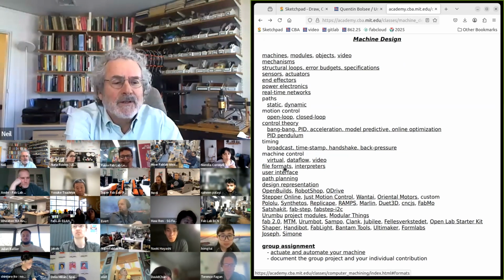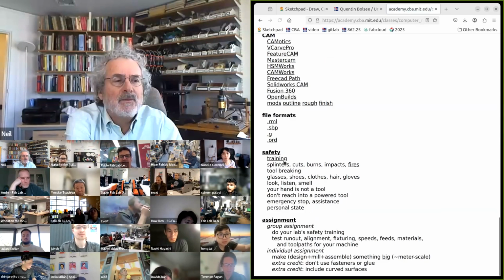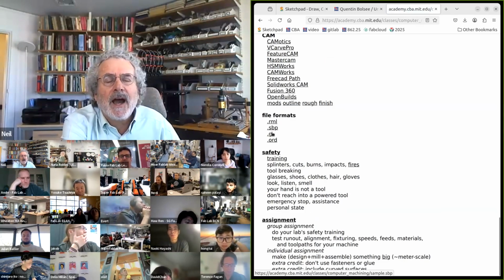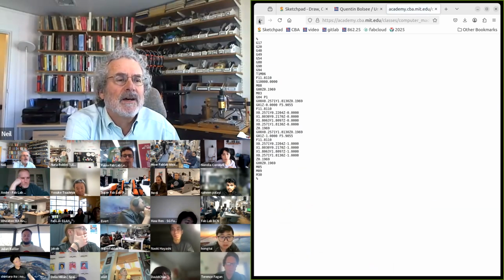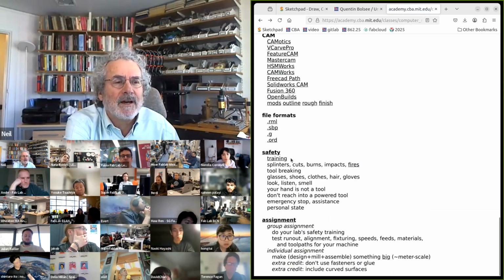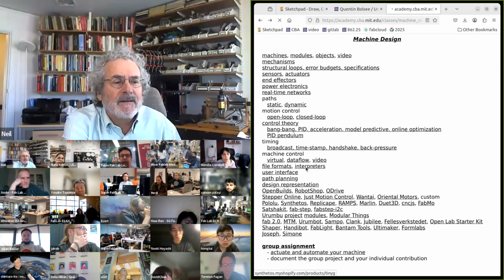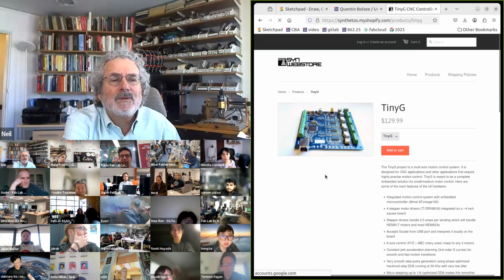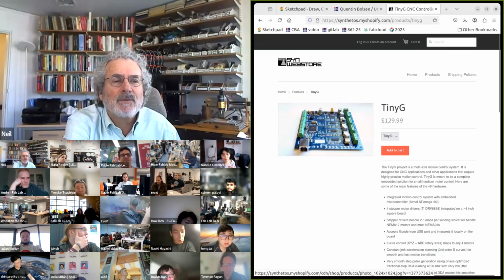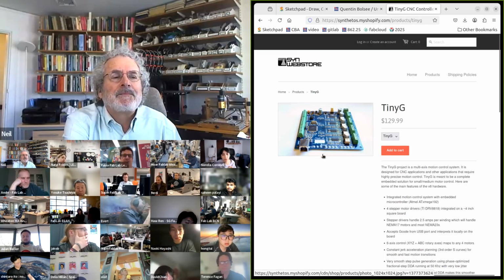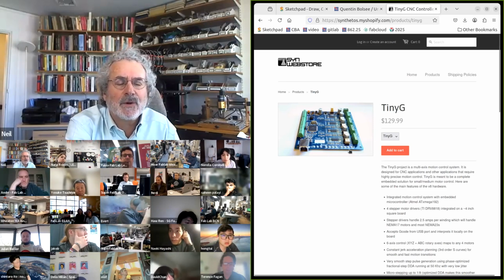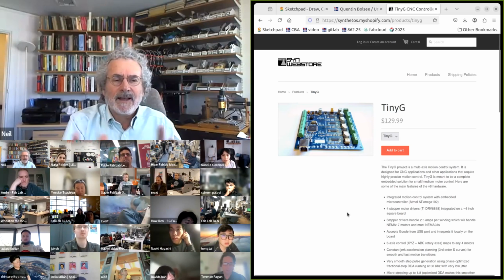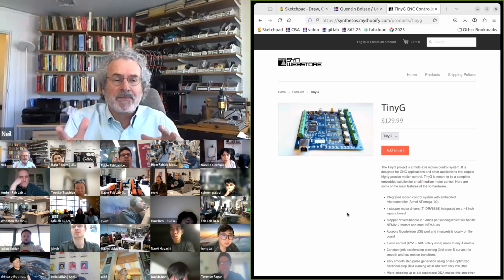So then you're going to talk to the machine. Most common commands are G codes, which are ancient, long past their due date, but still common. And then a common way to handle them is interpreters. So this is a common platform where it takes G codes in and then controls stepper motors. And so that's a classic version of it.